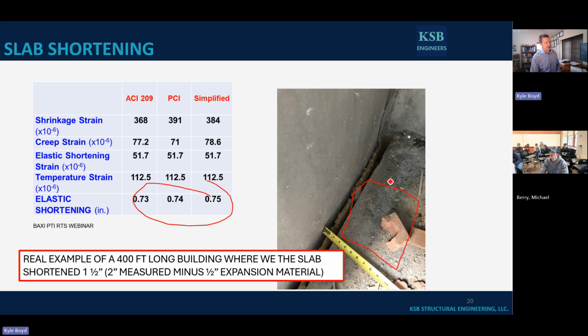Sometimes if it's in a parking garage though, and you designed it so this wall is self-supporting all the way up, you don't need it for lateral restraint. You're not dumping any shear load into it, and you've got a column right where I drew that column. You're fine with that gap.